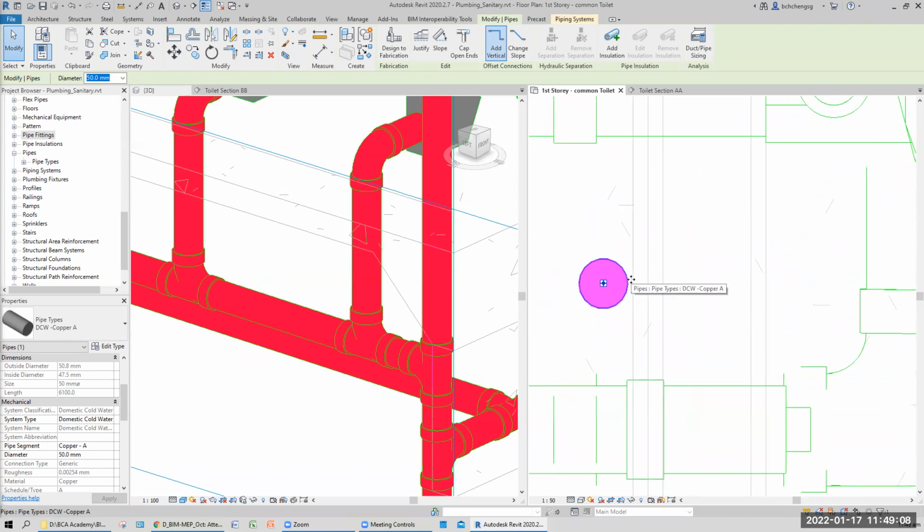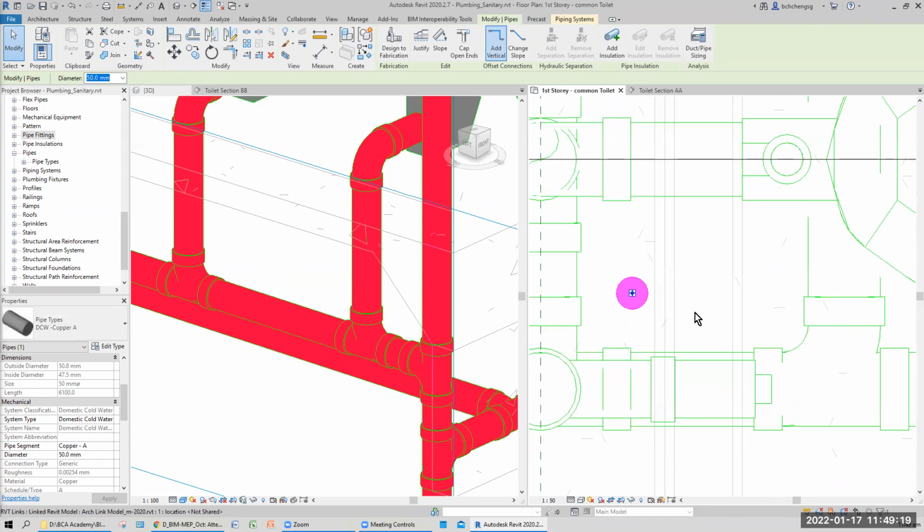Normally there's a space, we call the holder, unless you have a holder size. Currently I don't have, so I just assume that the space is there. Unless we need to source the holder, then we go and create it. Revit currently doesn't have it. So next time for construction work for M&E, that means you need to draw details. What is the gap distance between holders? Normally it's near the fitting corner. Then if it's too long, this pipe might sag down. So they must have support in between. So all these things will come later.